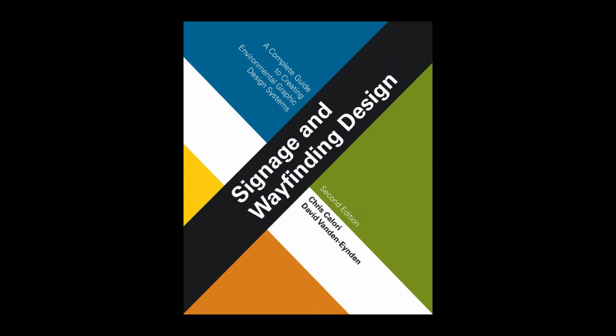In situations where there are no appropriately located existing structures for sign mounting, such as in the middle of a shopping mall's atrium or an open urban plaza, freestanding signs will be necessary, which naturally has formal consequences for the hardware system. It's also possible that the EG designer may find that freestanding mounting is completely appropriate for certain sign types, even when existing structures are available for sign mounting.